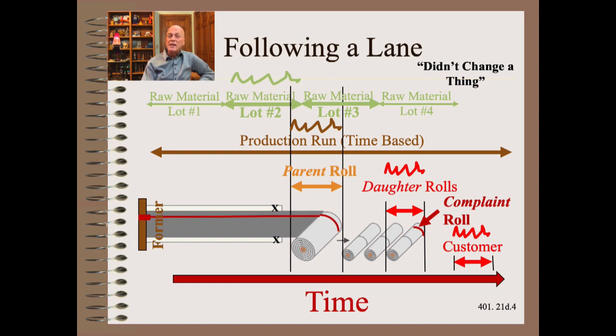So in this clip, we are going to take an entirely different approach. That is, to identify the element that was variable across the width. Variable across the width is called profile. In this example, we find that the extruder or headbox or other web former was risky in one location, near the drive side edge.